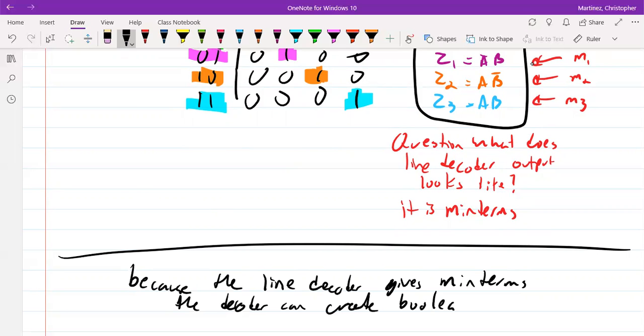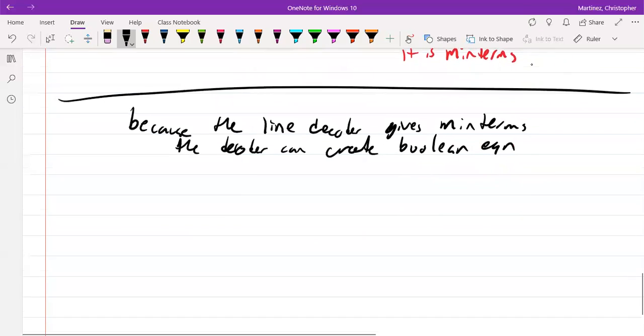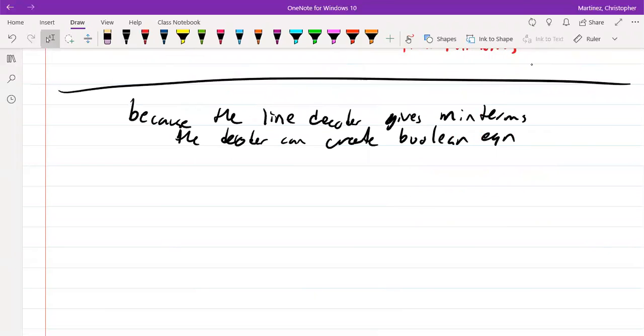So let's do an example here. And what this could help us save is, if I had a breadboard and I wanted to build a circuit going down to all the sum of products or product of sums, that could be a very big number of chips. The breadboard will be pretty large. We can get it a little bit smaller. So let's say we have 3 outputs we want to produce, an S, a T, and an R. And S, we know that it is minterms of 0 and 1.